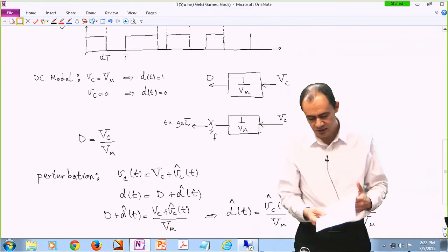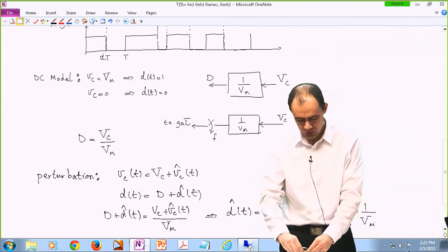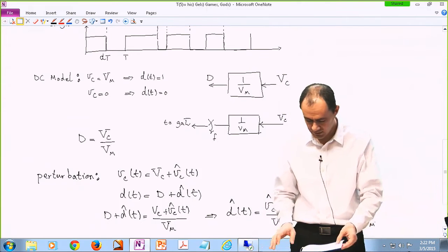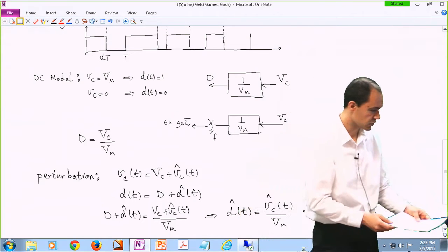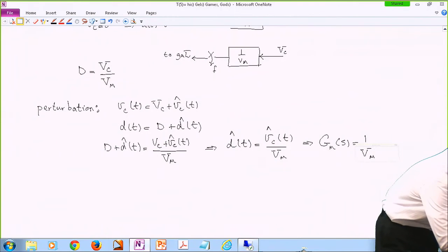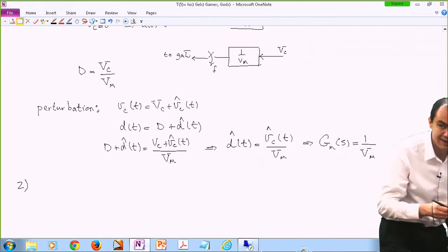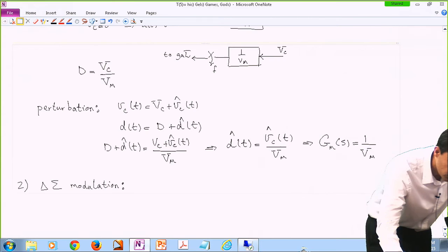All right, so this is how it is done most of the time, 99% of the time. But in case you are curious, they came up with this idea back in, for instance, the 70s. If you are curious whether it is possible to do it in other ways, the answer is yes. To give you an example, instead of doing an intersection-based kind of PWM, we can do a delta sigma modulation, basically. All right, the way this one works is